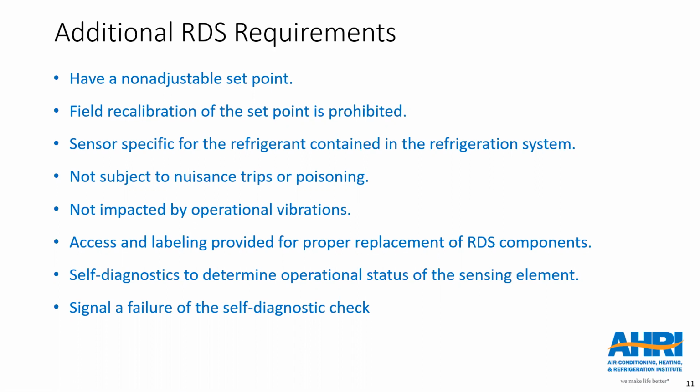These additional requirements are relatively consistent across the standards. Note that these requirements should result in A2L RDS systems that are what I like to describe as safe out of the box. No field setup, no field calibration or recalibration, and the RDSs are pre-qualified to meet the design standard by an independent testing laboratory. So thus no mistakes during installation or servicing, which is all good in terms of making sure that things work appropriately.